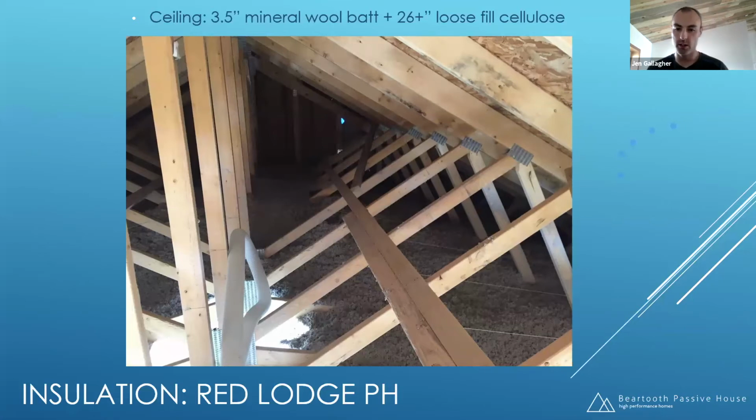Jessica asked, why did you decide to use mineral wool at the wall cavities? So we use mineral wool because no one around our area does any type of dense packing, whether that be fiberglass or cellulose. One, it's hard to find a contractor that will do that. And two, it's hard to find anyone who's done it at depths of more than 5.5 inches. So we didn't really want our 13-inch cavity to be a test wall for anyone. And I didn't really want to make that my first foray into dense packing walls.